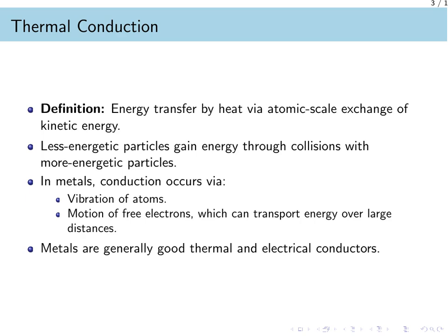Let us begin with thermal conduction. This is the transfer of energy by heat through atomic scale exchanges of kinetic energy. On a microscopic level, particles with less energy gain more by colliding with their more energetic neighbors. In metals, this process is particularly efficient because it happens through both the vibration of atoms and the motion of free electrons. Because these free electrons can transport energy over large distances, metals serve as excellent conductors of both heat